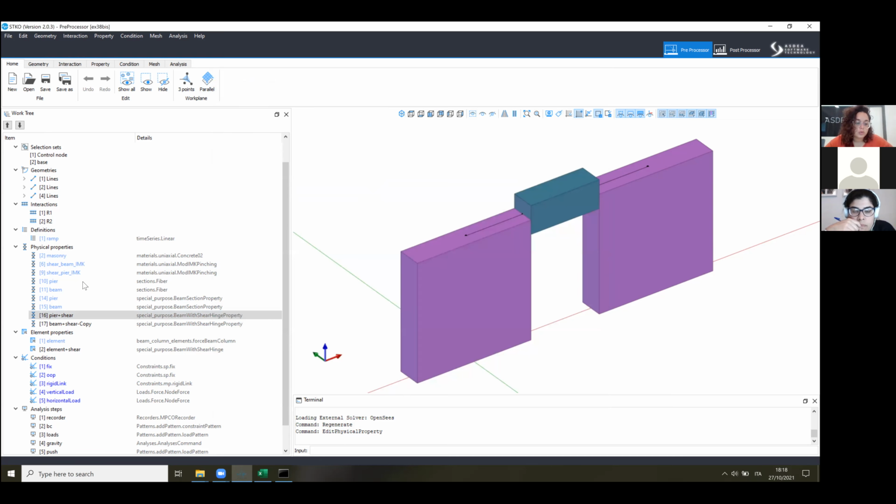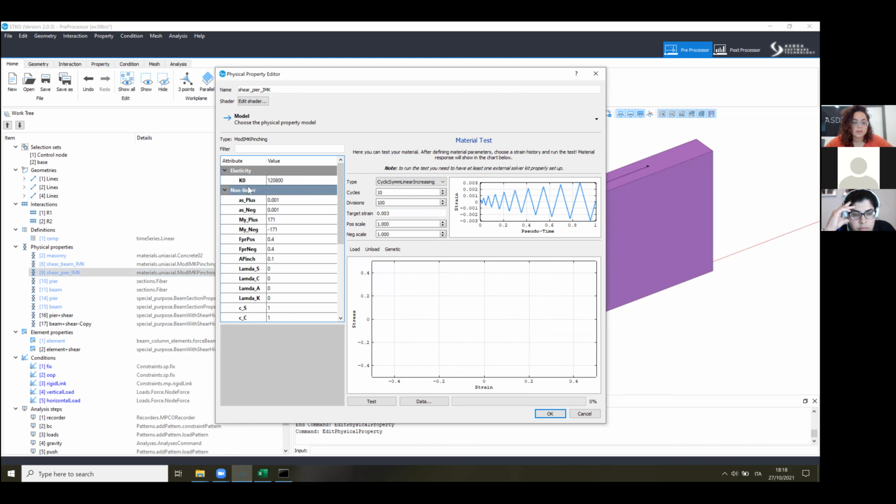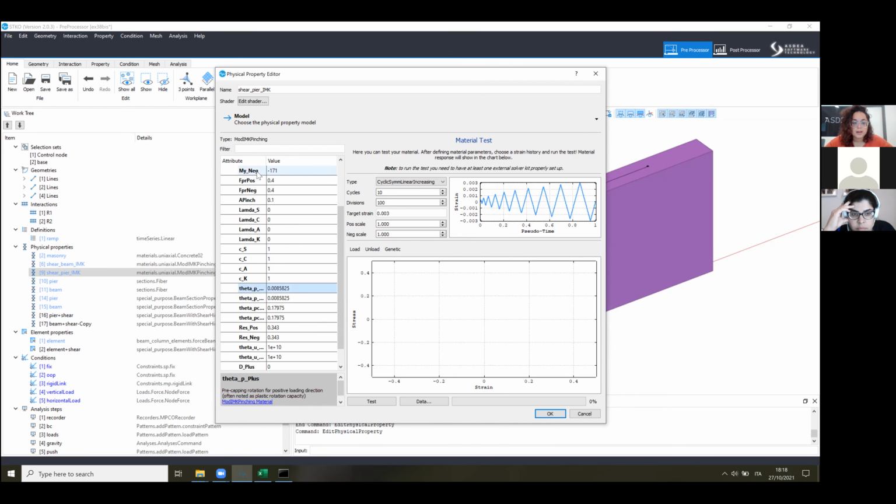And what do you do in order to use this? You can use the exact same shear law that you did before, but you have to divide your elastic shear stiffness by the length of the element, and also divide all the things that you had in terms of strain by the length of the element too, because in this case you're distributing the shear stiffness in a different way along the element.